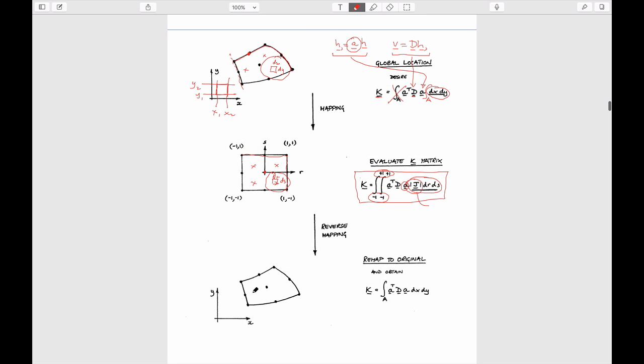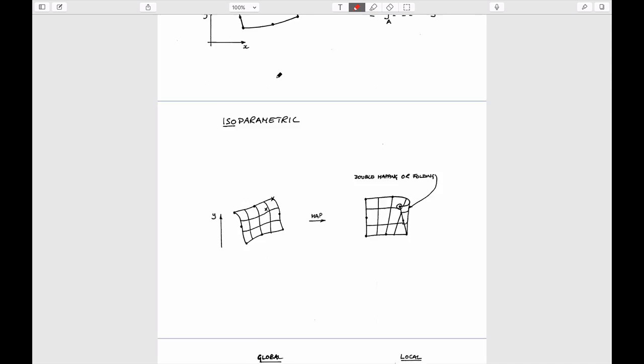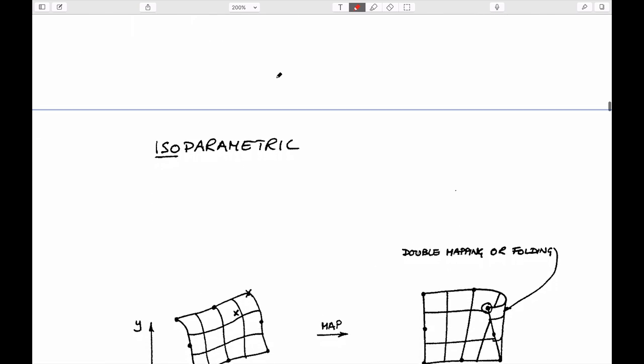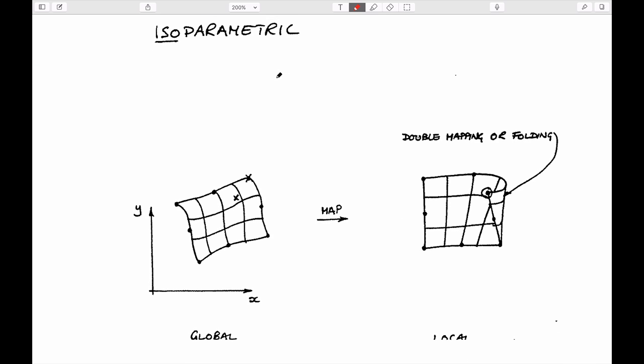And what it does is allow you to do two things. It allows you to use shape functions which are much more complicated and can represent, say, things like mid-side nodes and central nodes within the element, and also shape functions that will allow you to represent curved sides on things. And so those are the two things that we'd like to be able to do.